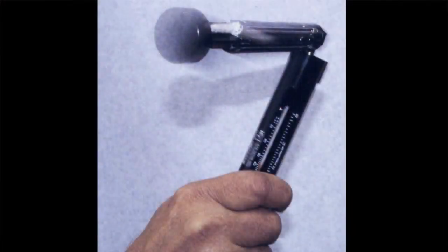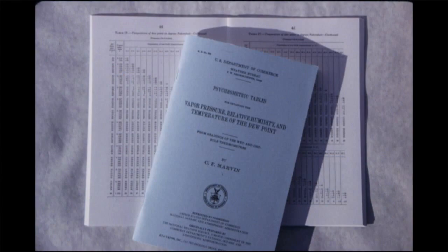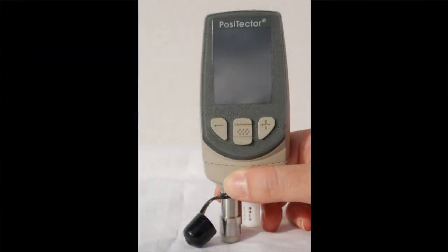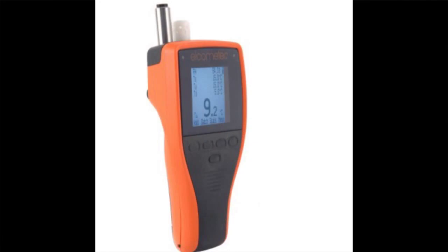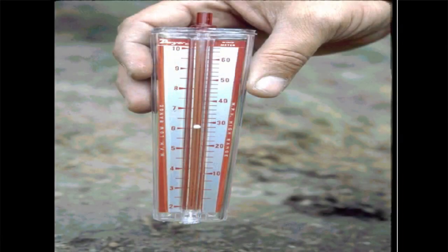These values can be obtained using sling or battery-powered psychrometers in conjunction with U.S. Weather Bureau psychrometric tables or surface temperature thermometers, or can be obtained using direct readout electronic psychrometers equipped with surface temperature probes. The wind speed can be monitored using portable wind meters or anemometers. You should not rely on prevailing conditions from a local weather service or from the internet, as conditions at the project site and the specific work area can vary considerably.